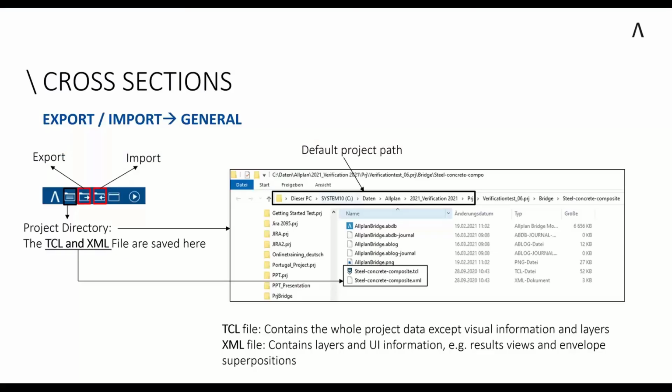Before I jump into the issue, let me just explain a bit the data management of Allplan Bridge. Whenever you start a project, it will be stored somewhere on your hard disk. So you can see here the installation and the project folder, and this is actually where your Allplan project sits. And in a subfolder of this, there will be another directory called Bridge, where there is the data of the Allplan Bridge project. So there are actually two databases, one for the Allplan project and one for the Bridge project. And the Bridge database sits in a subfolder of the Allplan project in the standard case.